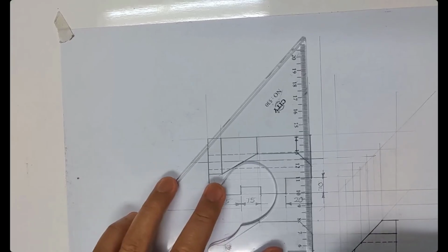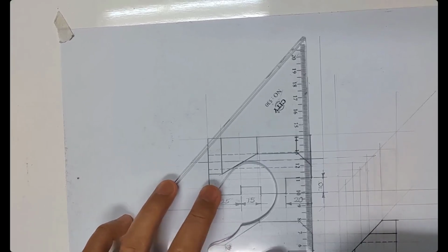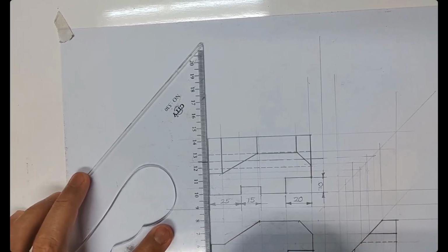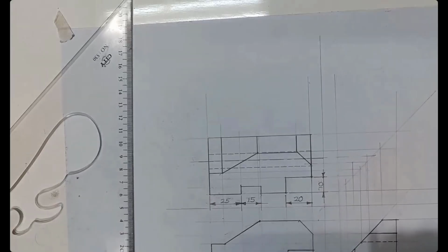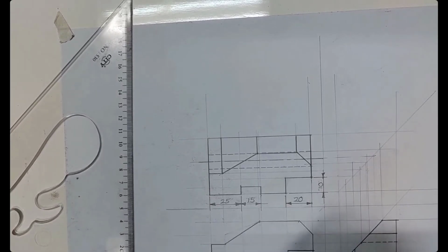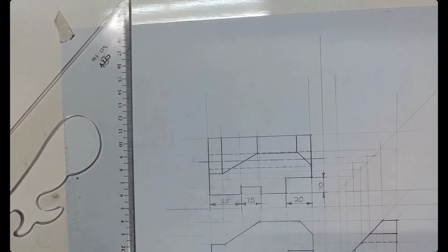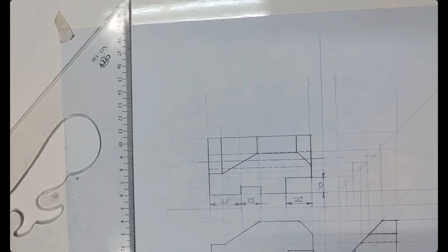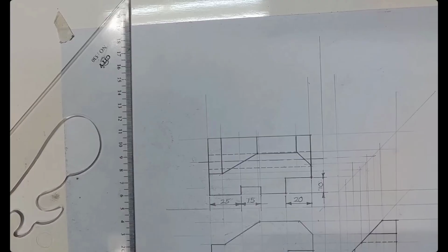So here, from this point, I'm not touching at the corner, get 1 millimeter, make extension line. What length? 2 letter height from the edges. So this will be your dimension line, arrowhead 3-1. Okay, I'm using 2B. Text is at the middle, 3 millimeter letter height, length is 80, right? 80, nicely. Wrong. This has an extension, a little bit.